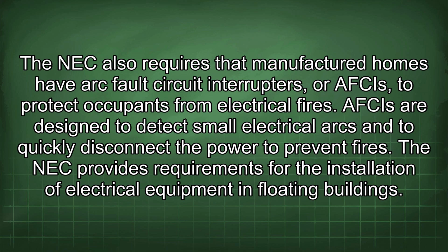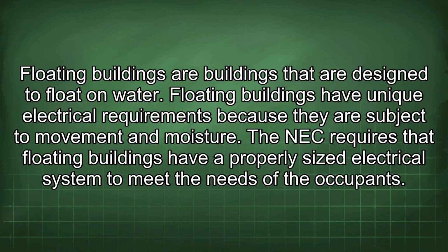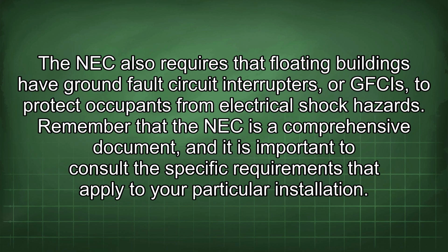The NEC provides requirements for the installation of electrical equipment in floating buildings. Floating buildings are buildings that are designed to float on water. Floating buildings have unique electrical requirements because they are subject to movement and moisture. The NEC requires that floating buildings have a properly sized electrical system to meet the needs of the occupants. The NEC also requires that floating buildings have ground fault circuit interrupters, or GFCIs, to protect occupants from electrical shock hazards.